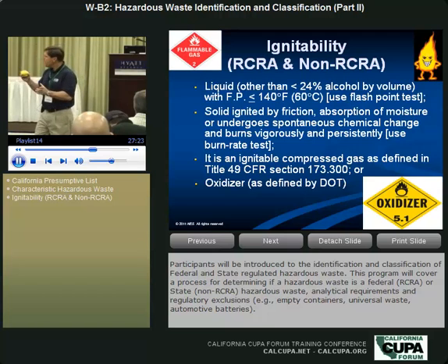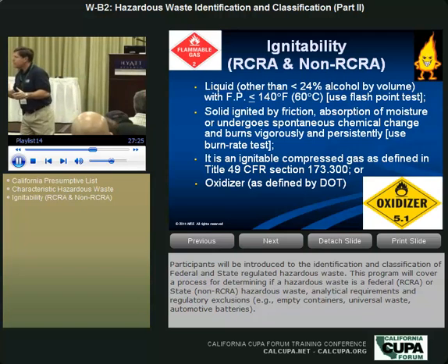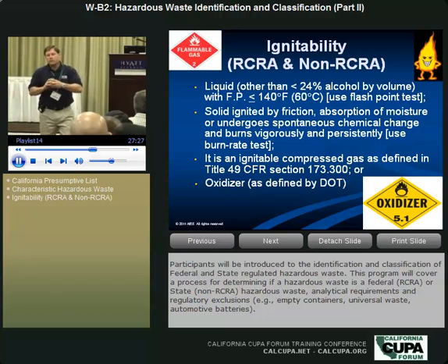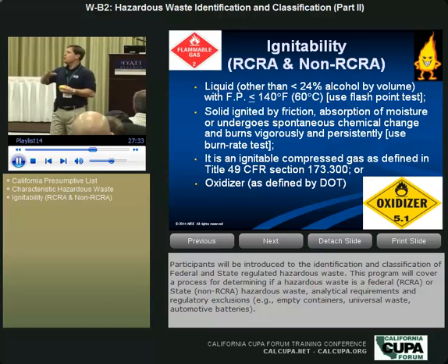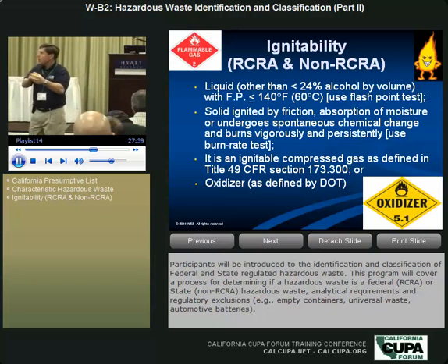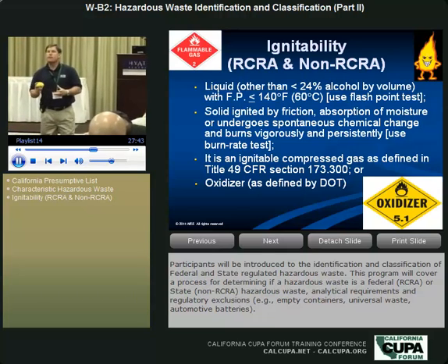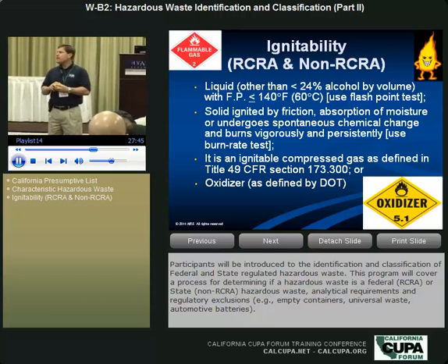It varies. Okay. So that rag that varies in its saturation that you produce, bench lab, bench scale, cleanup operation, wiping equipment, degreasing, whatever the case is. If it's not listed, assuming that it's not listed, and I don't think IPA is an F-listed solvent. I have to check. I don't think so.